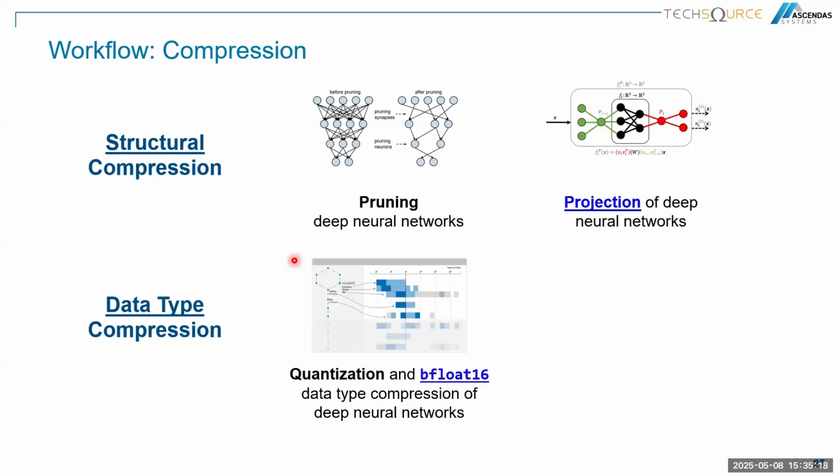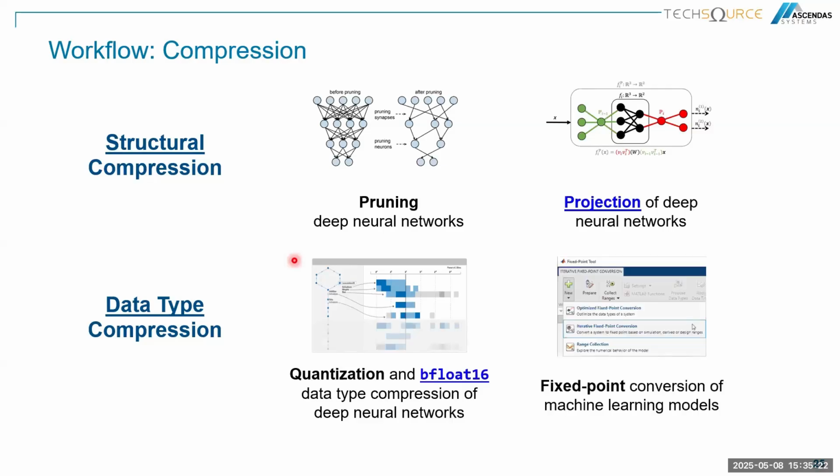There is also data compression. For example, we have a tool called Fixed-Point Designer. When you do the simulation, it is based on variable-step solvers to make it as accurate as possible. When you want to deploy to the MCU, the microprocessor, you need to convert it to fixed point.